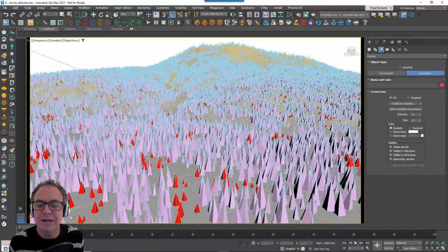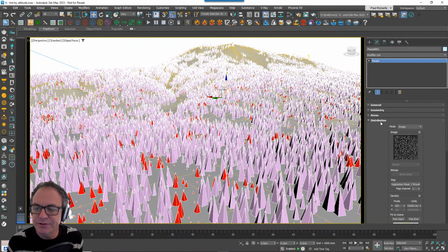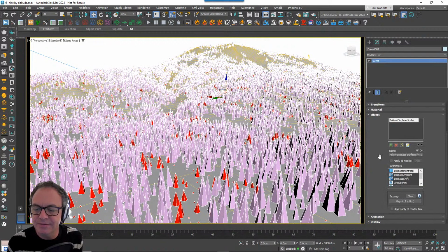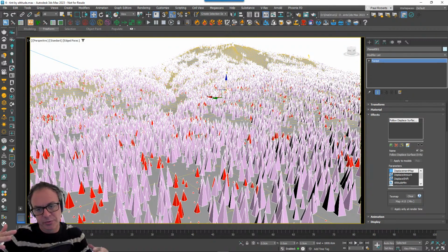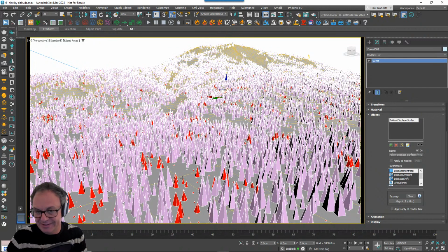So it's pretty straightforward, in fact. What I'll do is I'll come into Forest Pack, and I'm just going to scroll down. There's already a forest effect in here because this mountain has displacement on it, and obviously displaced geometry will change the shape of the mesh at render time, which the forest pack will ignore because forest pack reads the mesh before render time.